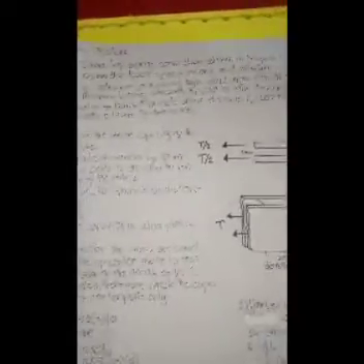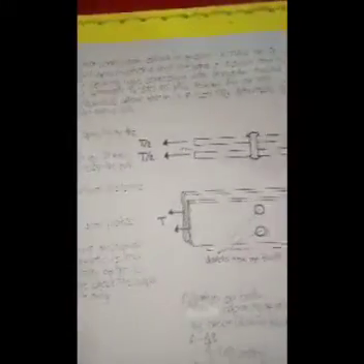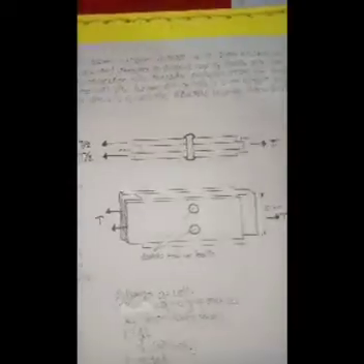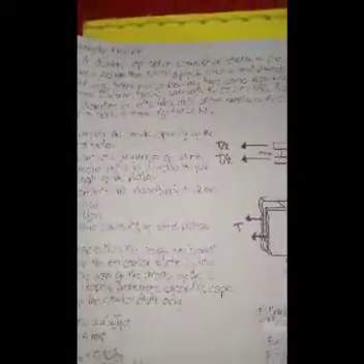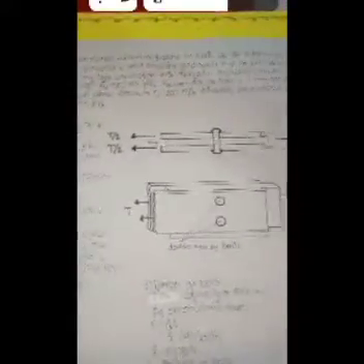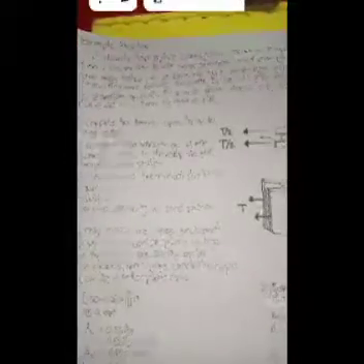So our answer is 141 mm. For problem number 2. A double lap splice connection shown in figure is made up of 6 mm by 150 mm and 9 mm by 150 mm. Use NSCP specifications and assume a double row of bolts with standard size holes for a bearing type connection with threads excluded from the shear planes.